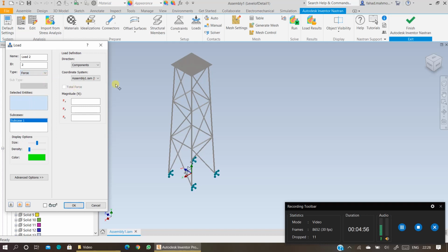If the loading is given to you as 30 kilonewton per meter, and the total height at which you want to apply the loading is 30 meters, you can just multiply 30 kilonewton per meter by 30 meters, and you will be left with 900,000 newtons of water wave loading.